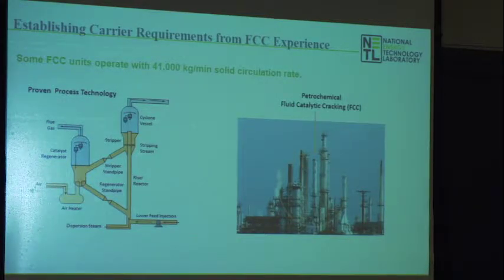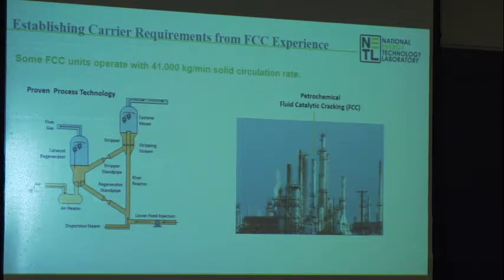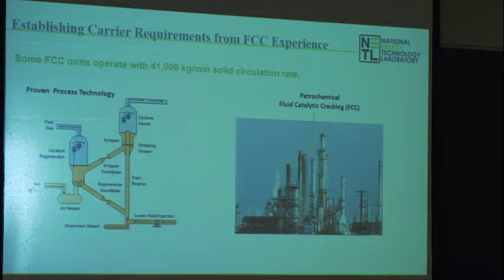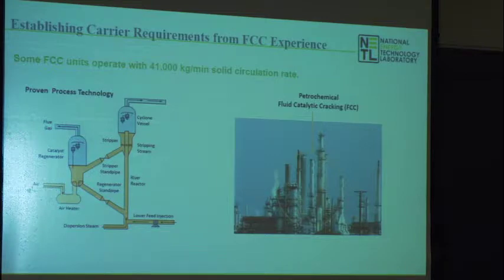You take a catalyst, and the hydrocarbon goes up this reactor with some stripping steam. You form a bunch of carbon on it. You're taking carbon out at that point, and you get the lighter hydrocarbons out of the top. That's how it cracks the stuff. And then you burn off the carbon, and it goes out as flue gas in the other reactor, and you keep recycling that stuff around. Fluidized catalytic cracking, the chemical engineers just love this stuff, right? That's their whole business, improving things like that. It does have very large solid circulation rates at temperatures almost comparable to what we do in chemical looping.